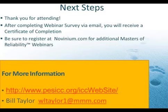Good question. I would say probably the majority are due to improper cable prep, and most likely not stripping off the semicon correctly, either putting a knife cut in the insulation or something like that. We do see them where they are misapplied.